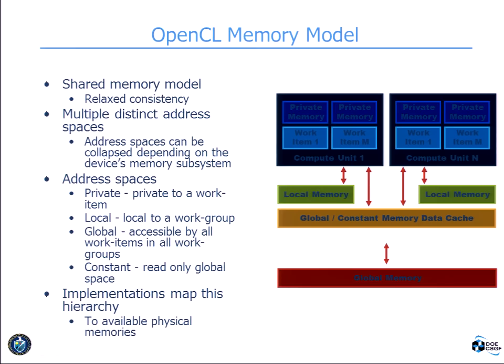In a GPU type system, you basically have to schedule all this. So you have to pull a piece of data out of global memory into perhaps the on-chip global memory, or put it in the local memory of your compute unit, which can't be seen by compute unit N. It can't access this data. And so you have to schedule all of that data transfer if you write this manually. And then you have to actually schedule the work onto these different compute units and basically use the local memory, register files and such that you have in that compute unit.